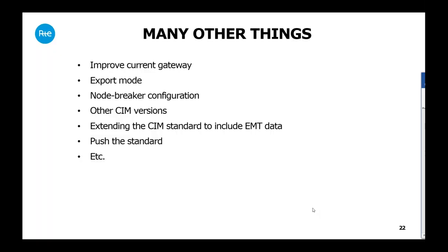Sometimes the issue becomes more and more complex for high frequency transients. In the case of a line segment in CIM, we can add additional data like the representation of towers, insulators, grounding impedance, etc. We also have a surge arrester model implemented in any EMT tool, but there is no CIM equivalent to surge arrester to date. So this gives an insight into the complexity of converting EMT data to CIM format.